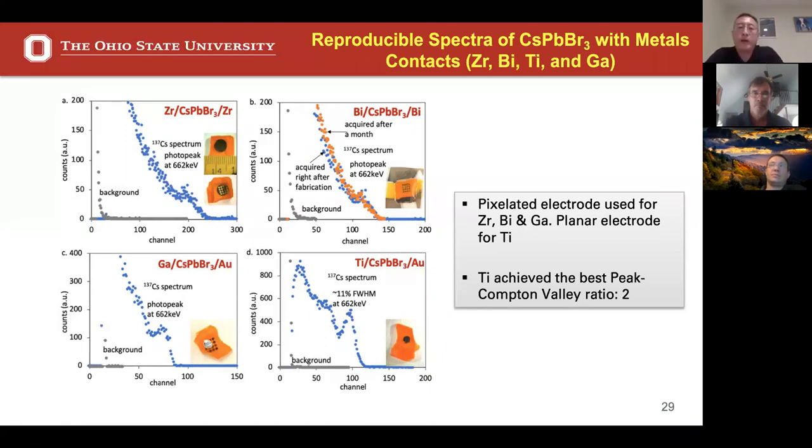We want to reduce the possibility of crystal-to-crystal quality variance affecting the detector's performance. But after every polishing and washing, layers of material are removed. For us, judging whether it's good or bad is really just by looking at an IV curve after metal deposition. So we did not look into any other surface properties.